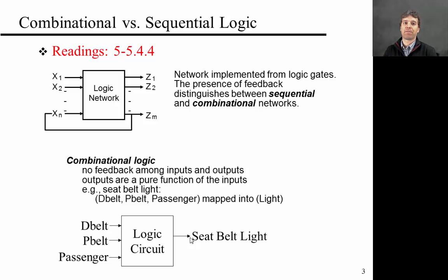That's feedback. And of course that system could also have external inputs. For example, if there's a sensor that detects whether a car is present or not, that influences when the light switches, that can be added to this sequential circuit. So the essence of a sequential circuit is that you have a combinational network that does some logic computation on the inputs, but there's also this element of taking outputs, or information about the current outputs, and feeding it back into the system.